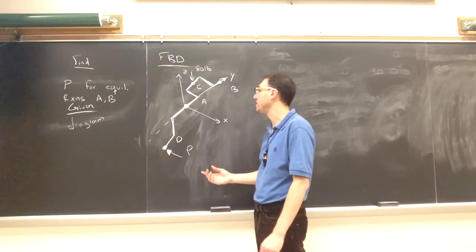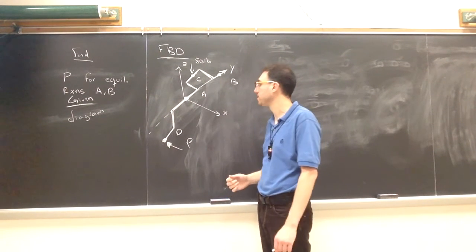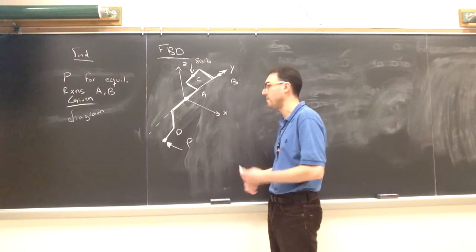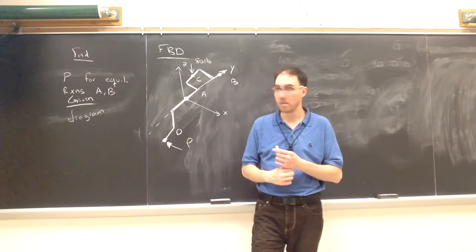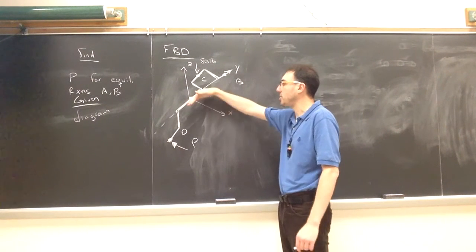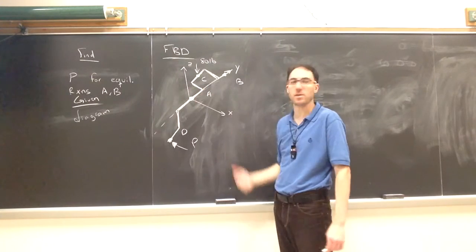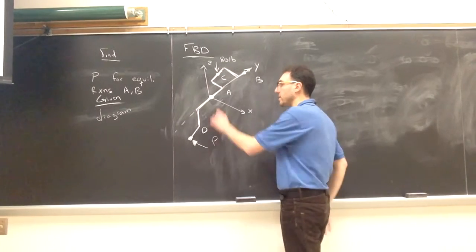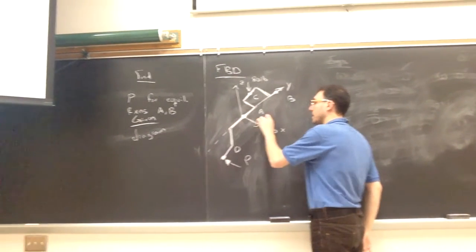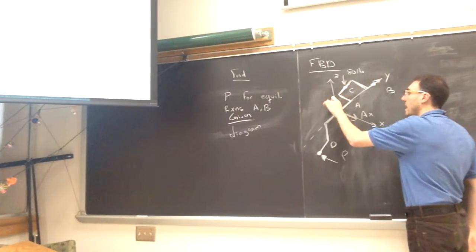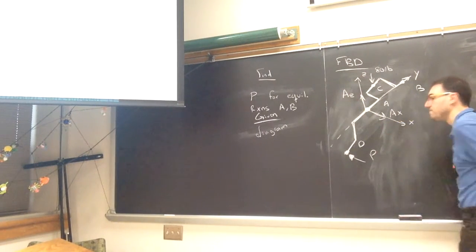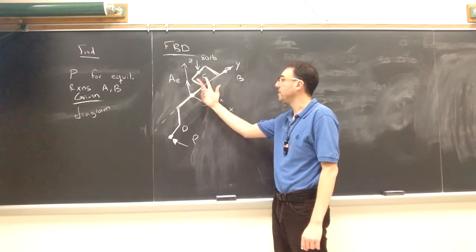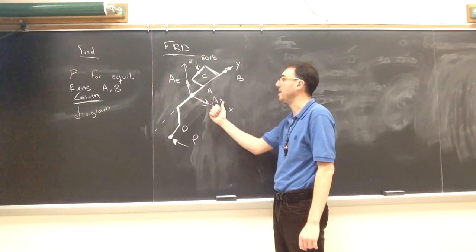Therefore, we're not going to put a force along the y-axis. However, what motion does that bearing prevent from happening at point A? Right, the shaft can't move along the z-axis and it can't move along the x-axis. That whole xz plane is prevented. So we model that as a component of a force in the x direction and a component in the z direction. One direction is allowed, the xz plane is prevented, so I model that as the X and the Z.